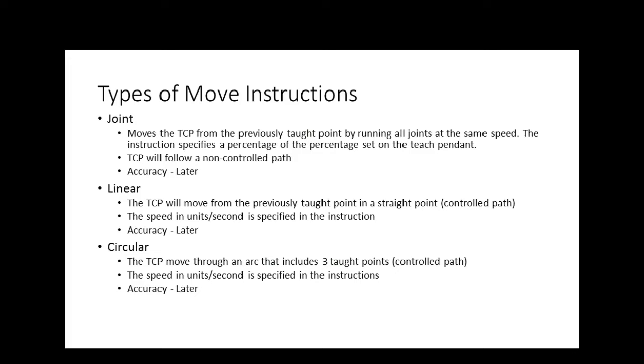So normally what we use this joint move for is we're going to start the robot in what we call a home position or a start position, and then we're going to be working down here. Usually we use joint moves to get it down to where we want to go as fast as we want. And then how fast we move it on our workpiece depends on the job, right? Does that make sense? So all we do on a joint move is we specify a percent speed. You don't specify the speed, you specify a percent speed. So if you have your teach pendant set to 100% and you tell it to do a 100% speed move on a joint, you'll see the robot move as fast as it possibly can. So some of these robot moves on the big FANUC over there, these are joint moves.